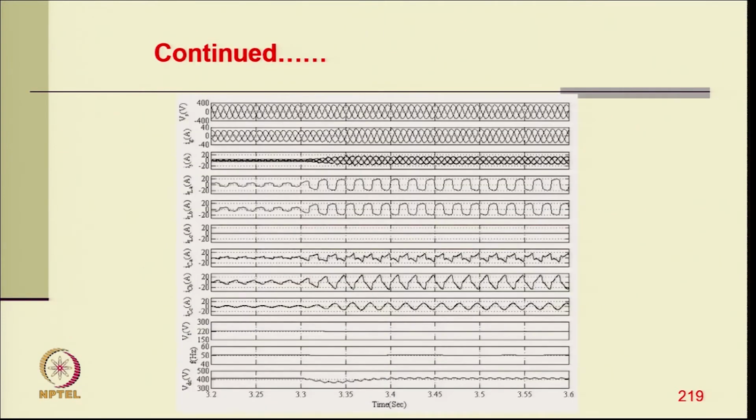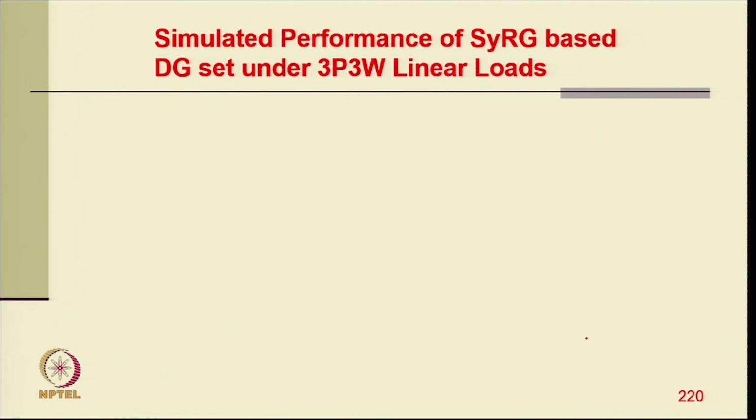Then we have a non-linear load on this system, a lower load, but the generator current and power is not less than 80%. Here we have a non-linear load, so we provide the harmonic analysis as well as load balancing and voltage regulation. All those features are demonstrated here, and the terminal voltage is regulated, and frequency is also regulated.